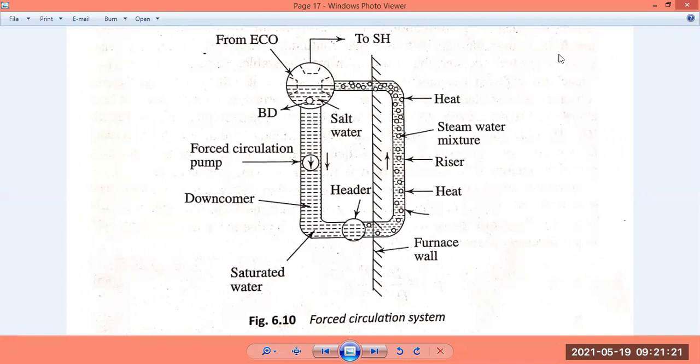The amount of heat released by burning the fuel, it takes away almost without any wastage. Although the furnace is properly insulated, there is nothing like perfect insulation. So as much as possible, the heat generated is taken out of the riser walls inside the fluid itself.